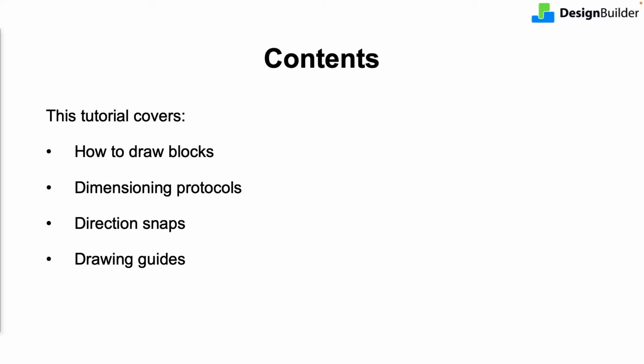Hello, in this tutorial we'll introduce you to blocks and dimensioning protocols in DesignBuilder. During the tutorial we will show you how to draw blocks, understand dimensioning protocols, and use direction snaps and drawing guides.